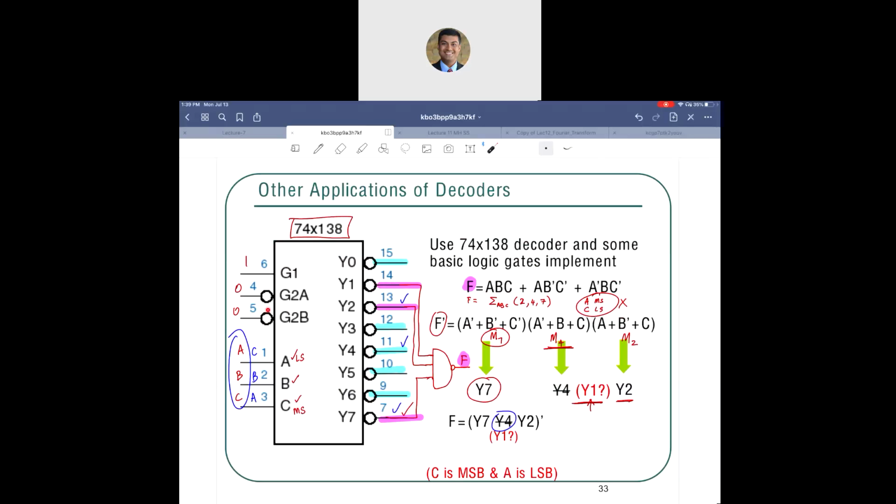So component 1 is from task 1, and you would have to just add a NAND gate in front of it, make those connections. So when you're writing the structural model, you again have to use the same 3 steps, right? Component declaration, component instantiation, signal declaration. So you can do task 2 that way. Please refer to this example. Depending on which minterms you have, it'll just be connecting those guys to the NAND gate.